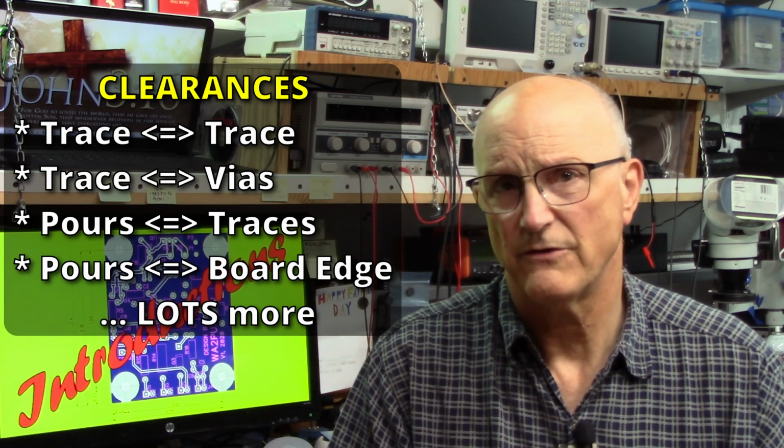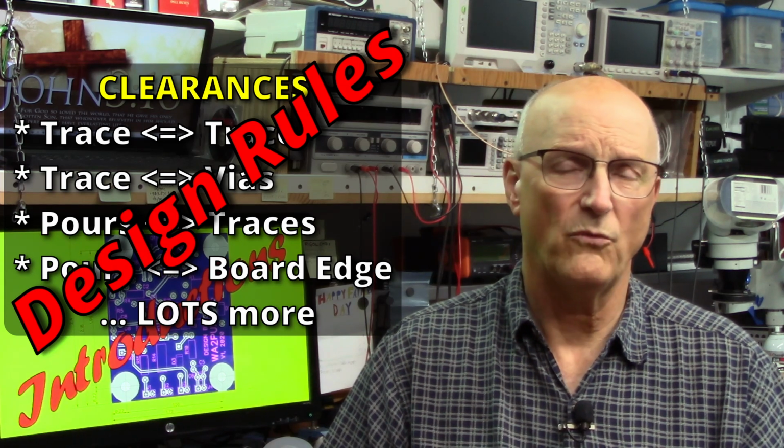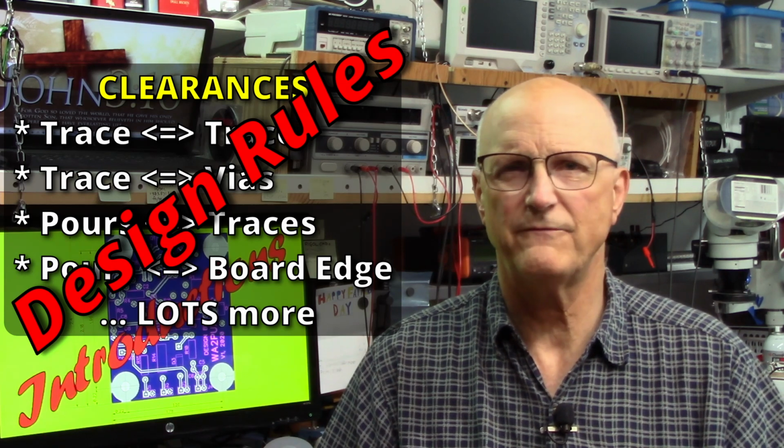And all of these things are defined in what are called the design rules. While you can make them whatever you want them to be, generally it is a good thing just to use DipTrace's defaults, as these work for most board fabricators. With that said, if a particular signal or power trace requires something other than the default settings, you can define all of the special parameters for a given net on a PC board, which include things like the trace width and the clearances and all kinds of stuff. And this is an absolute must if you're going to use an auto router.